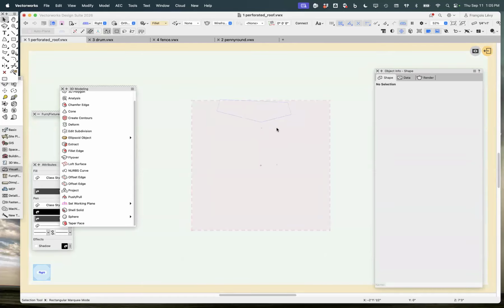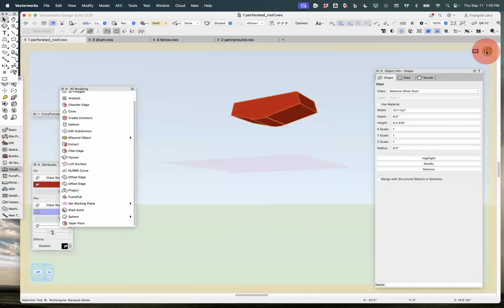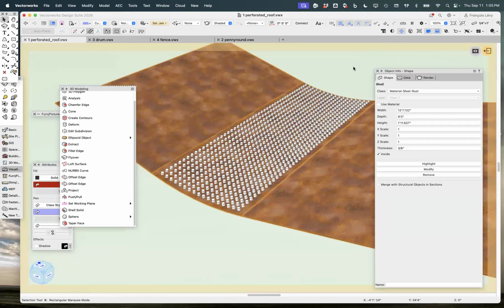Now, what I'm confused about is you made the curved metal, and now you needed a 3D NURBS surface upon which to make the array, and you couldn't do it on the metal because the metal has thickness, so you extracted the surface. Correct. At the moment you extracted the surface, you had the metal with thickness and you had the surface, two different things.